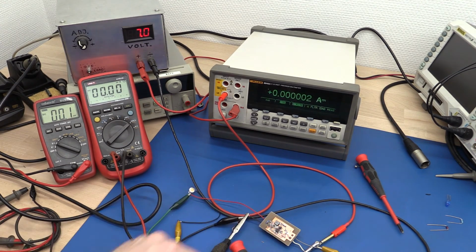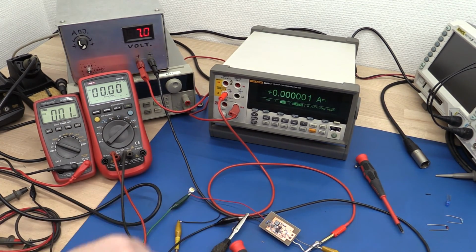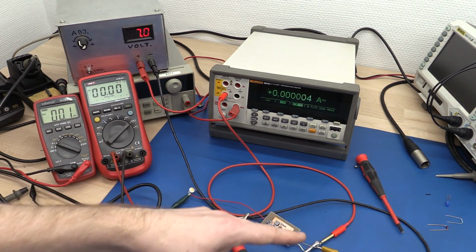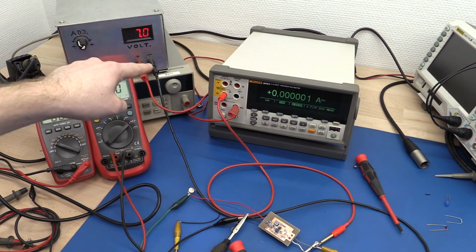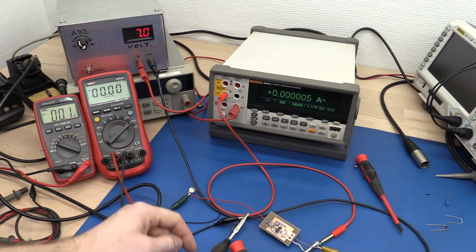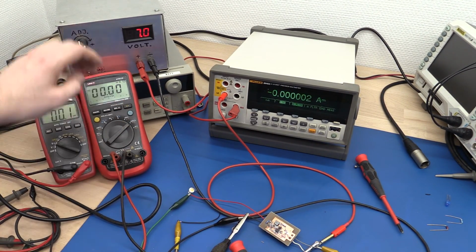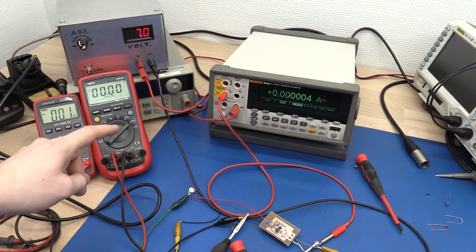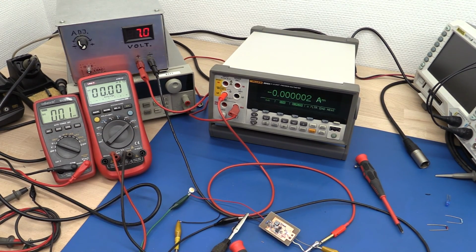It might be the diode that I'm using that's not really up for the job, and also perhaps there's too much losses in some of the other components. And maybe the switching frequency is not really right for the inductor. Also there might be some drops in the leads here that I didn't take into account. It shouldn't be that much at 200 milliamps. And this reading could be off by 50 millivolts. It's not high precision testing, it's just kind of getting the idea.